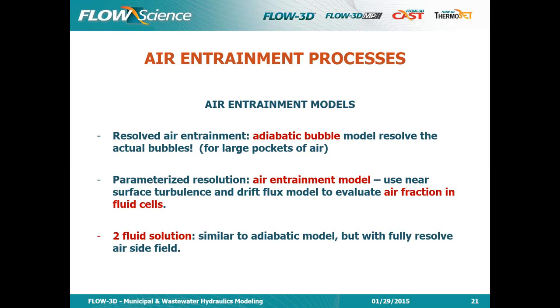One option is to resolve the bubble itself. That's for large bubbles, pockets of air. So we have an adiabatic bubble model which resolves the whole thing. Then we have a parametrized solution, called the air entrainment model, which uses near-surface turbulence and what's called the drift flux model. What we evaluate, rather than single individual bubbles, is the total air fraction within a fluid cell. So this is a very fast and very economical solution, but it's also a very good solution for many cases. And when you need extreme detail, we have a two-fluid solution where you not only resolve the water side of things, but you fully resolve the air side of things. I'll show you how this works.